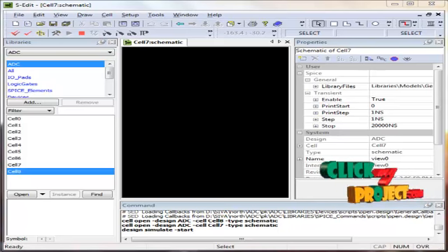The differential amplifier is most often used with the current source load. If the gate voltage of M1 is greater than the gate voltage of M2, then the drain current of M1 increases with respect to the drain current of M2. This increase in drain current of M1 implies an increase in drain currents of M3 and M4. Therefore, the only way to establish circuit equilibrium is for the output current to become positive in voltage.